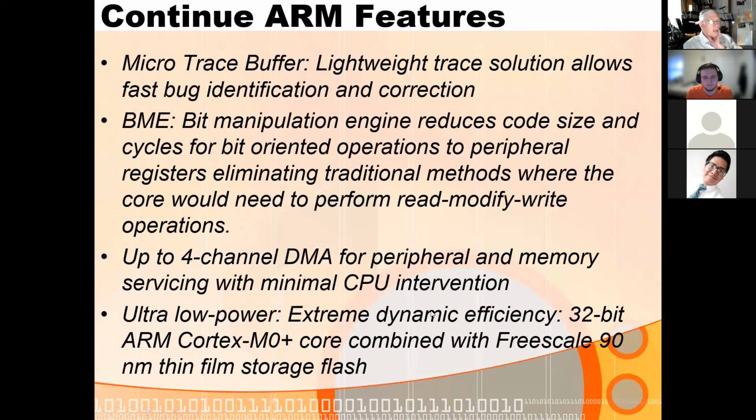But as these chips get pushed lower and lower, the leakage currents are going to go up. So some of the advantages of turning off the clock to these modules might disappear. But normally, most of the power is used when it switches. All right. And this chip is just an extremely ultra low power chip.